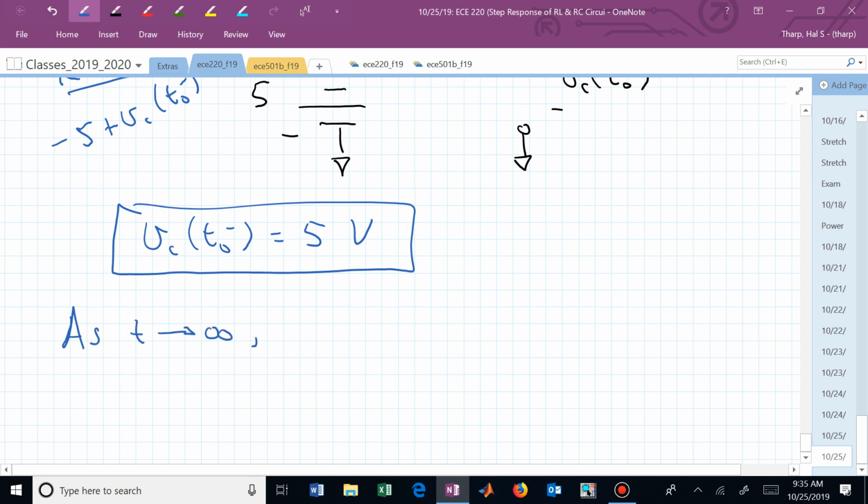And we'll get just kind of loose and we'll just say, I want to know what is V sub C at infinity. And we now know, since we're in the know, that doesn't take very long necessarily, does it? After the switch happens and we have this system excited with constant sources, how long do we have to wait? 5 time constants, 5 tau. Then we're down to e to the minus 5, which is less than 1% of where we started.